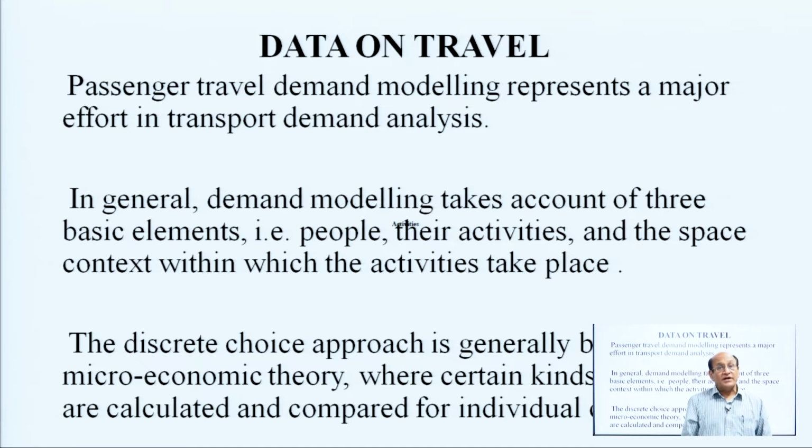Now, come to the next one, which is data on travel. Passenger travel demand modeling represents a major effort in transport demand analysis. As we have discussed, the models are sequential: trip generation, trip distribution, mode split and trip assignment, and this requires basic data for their analysis.